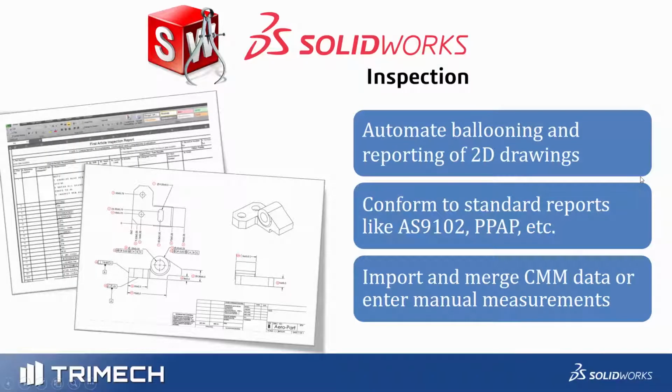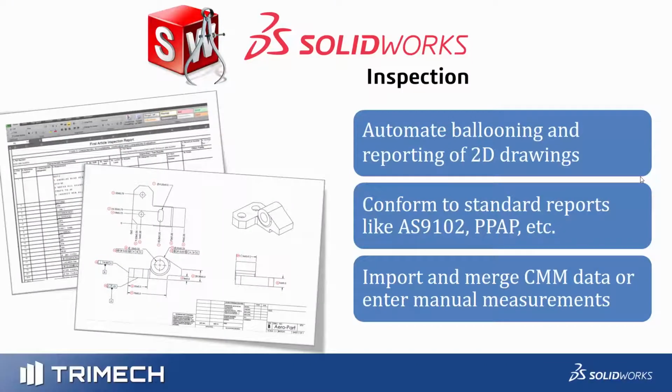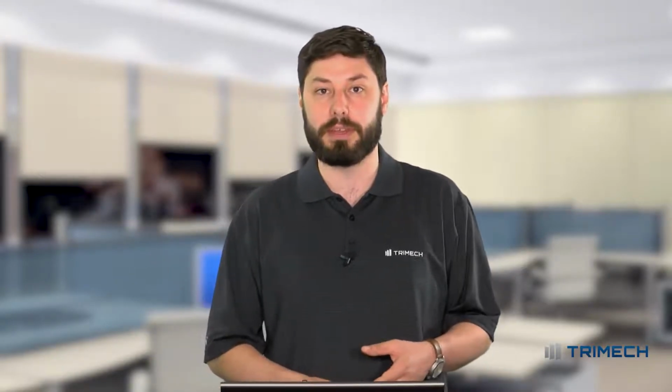So SOLIDWORKS Inspection allows us to automate both the ballooning and report generation directly off of drawings. And this allows us to do all of this information directly off of either SOLIDWORKS prints or PDFs, as I said before. And what this allows us to do is to conform to any sort of inspection standards like AS9102 for aerospace or PPAP for automotive. One other key aspect to SOLIDWORKS Inspection is that you can also import that data and merge it together with things like CMM or digital calipers to track the measurements on your quality documentation.